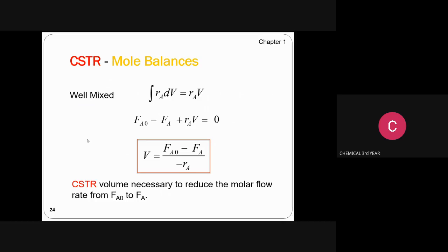Before that, we have to understand what applications are used in the environmental field by using the CSTR equations. One is the activated sludge process of wastewater treatment, and the next one is the lagoon treatment system for natural wastewater treatment. The last one is the anaerobic digester for the stabilization of wastewater biosolids. In chemical engineering: loop reactors for pharmaceutical production, biogas production and fermentations.